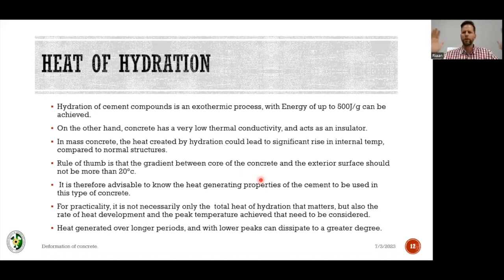And if the concrete dimensions are massive enough, you could sit with a very real situation as a problem presenting itself as heat of hydration. So it's not just, it's a high-end performance concrete, we might have risk here. You could have heat of hydration considerations in a 20 MPa concrete. I'll tell you a story about that one as well.